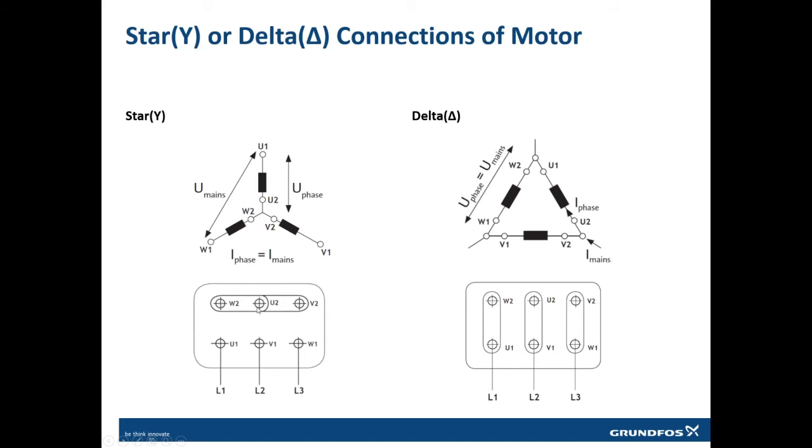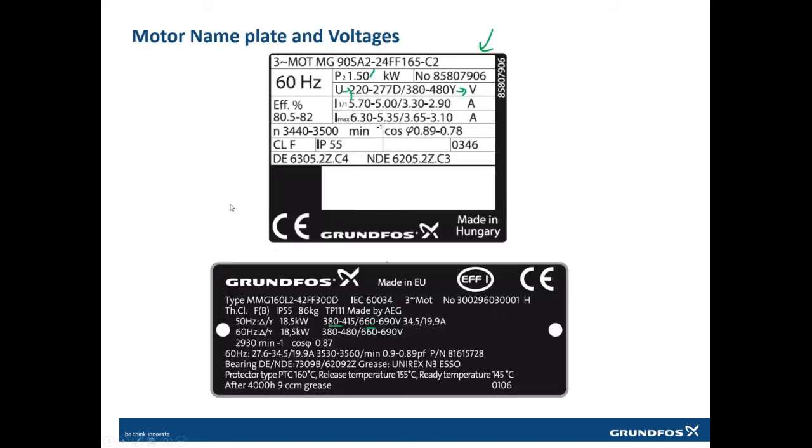then we will have 2 resistances in our path. That means the current will enter through here, pass through resistance 1 and resistance 2, and go out. That is the path of the current. You have 2 resistances in a star connection, so it is a higher resistance, and you need more voltage to generate the same electromagnetism, to power 1.5 kilowatt.